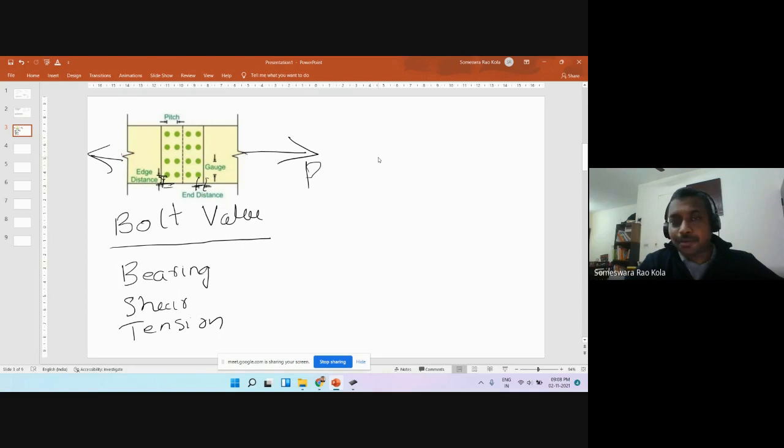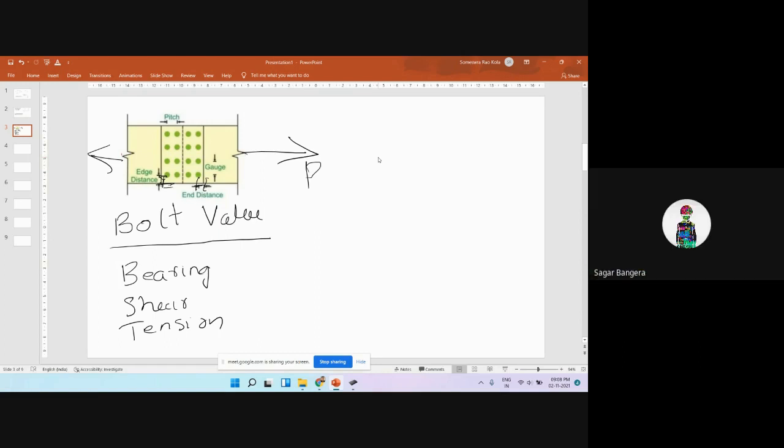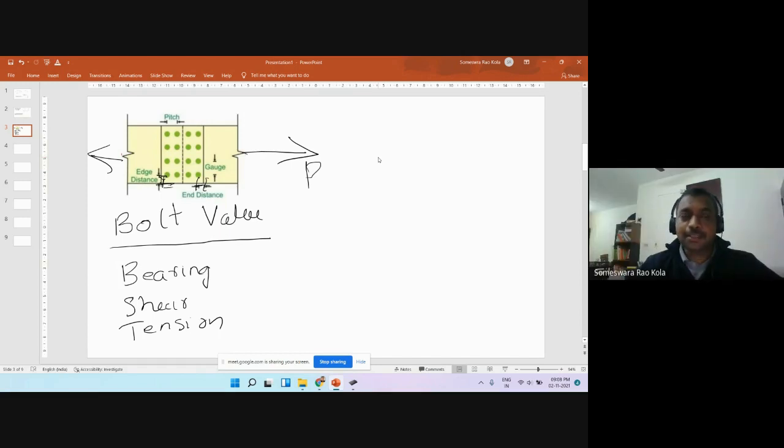Any specific example that you can think of? When bolts are used in stanchions due to uplift. Due to uplift. Perfect. Yes. And also when you have these HSFG bolts, wherein the load transfer is primarily through friction, but again that will get converted to tension alone.